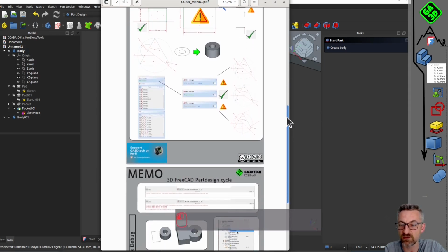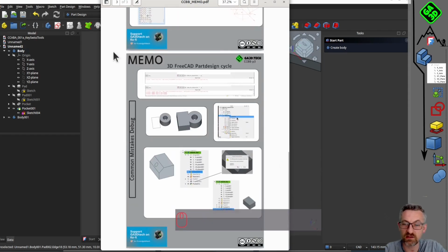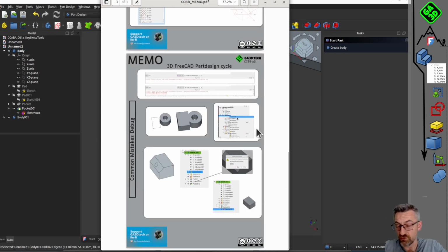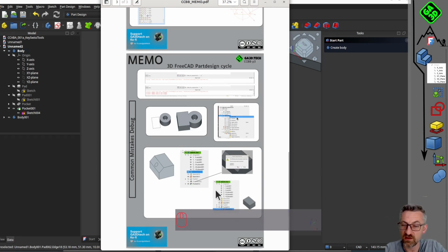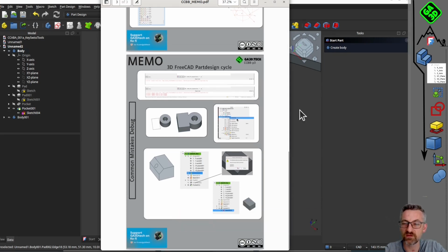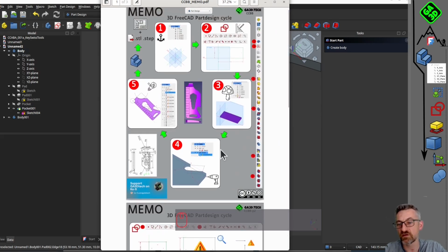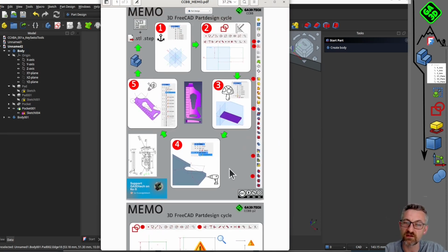Things to watch out for. In Sketcher, try to get all your sketches fully constrained. Green. I won't drown you in every possible issue, but stay alert and develop your logic around them. Common issues include open sketches, unintentional feature activation, and volume creation without proper connection to the base part. Be especially careful when modifying a model later.